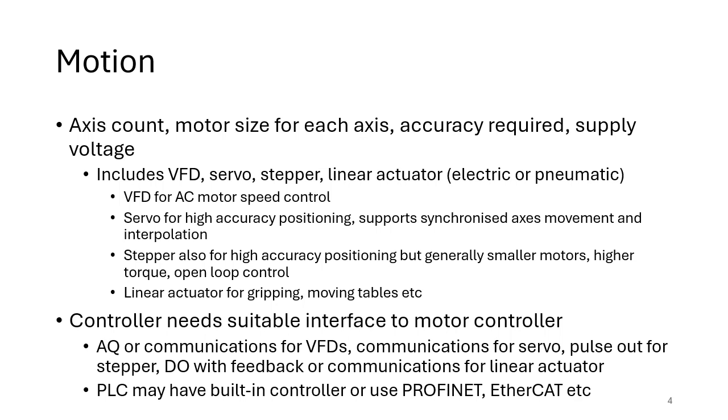VFDs, PLCs may even have a built-in controller, or they might use Profinet or EtherCAT, etc., or there might be some modular motion controller which you might use. So again, you'd need to look at the PLC vendor to determine what the motion control capabilities are.